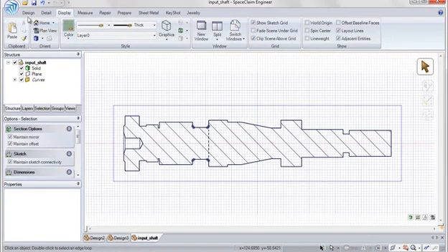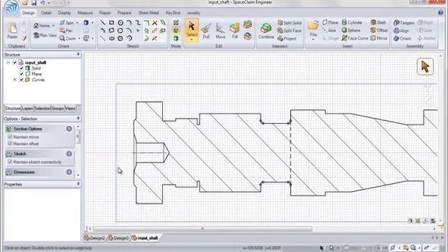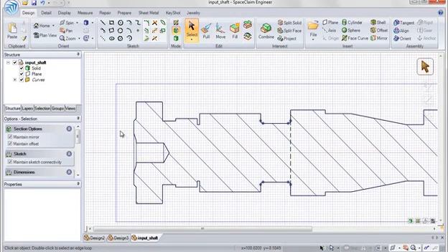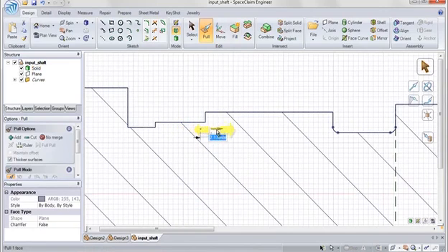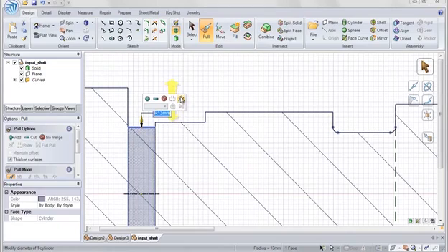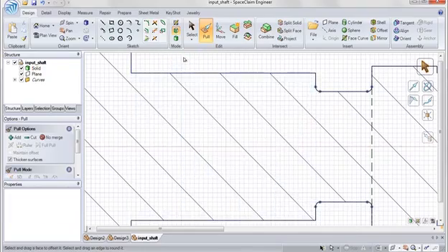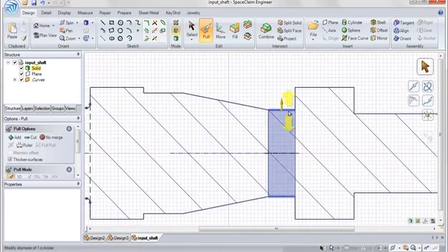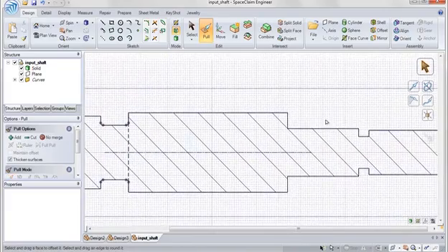And we'll make a couple more modifications to show off the first step in this manufacturing process of the turning operation. So I'm going to go ahead and maybe get rid of that end hole using the fill command, and we'll get rid of some of the detail here using the pull command to pull up to reference some of this geometry, simplifying our model. Getting this prepared for the rough turning operation. Again, using pull up to and the shift reference.